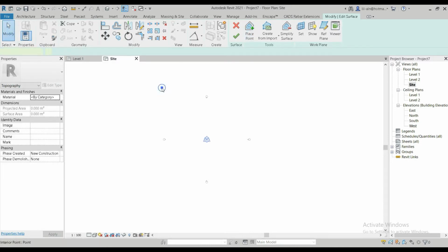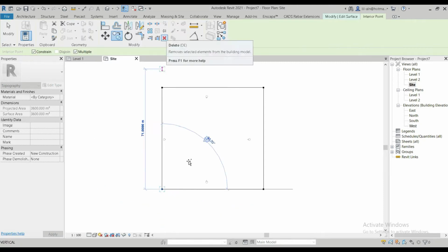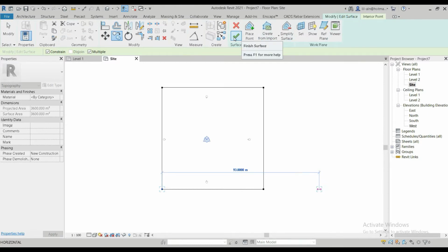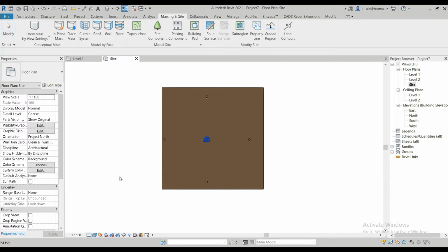So as usual, Revit and a metric architectural. The first thing you do is units. It's always the units, and after that we change the units to meters. Similarly, then let's go to massing and site. The topography is the first thing that we change, and let's set that to 60 meters.